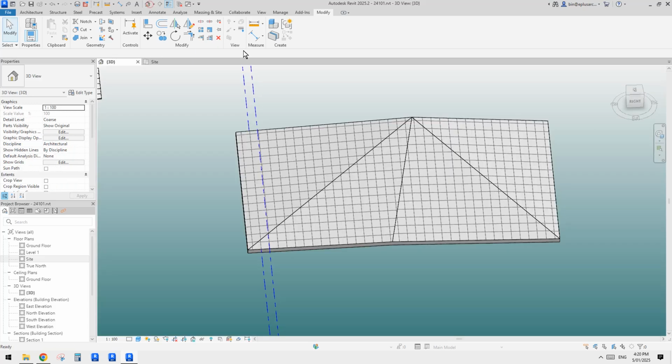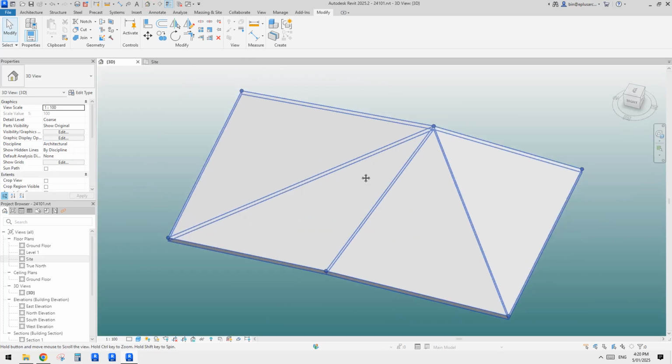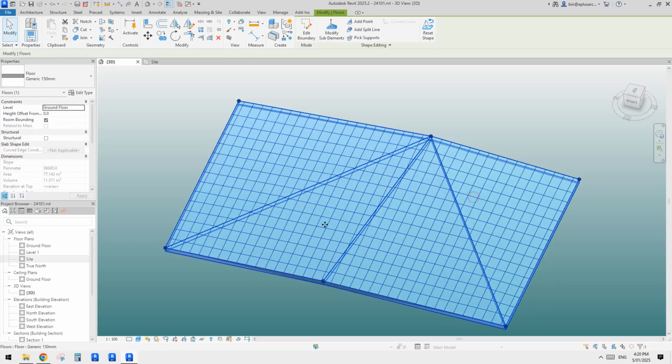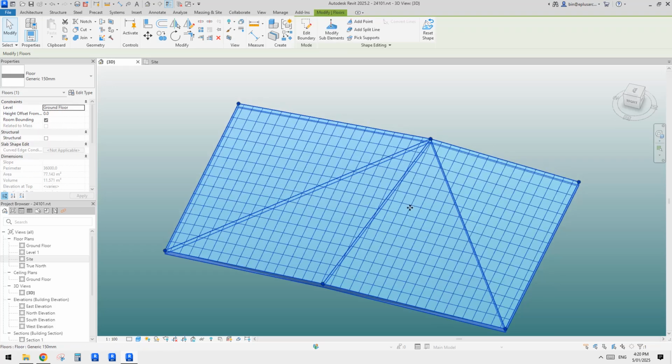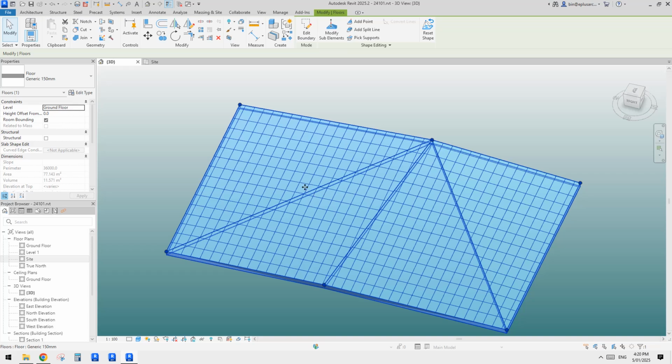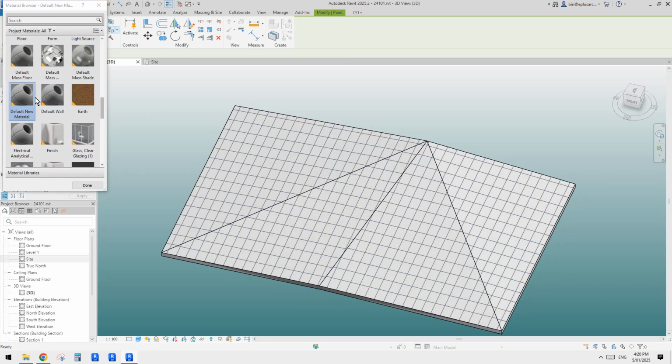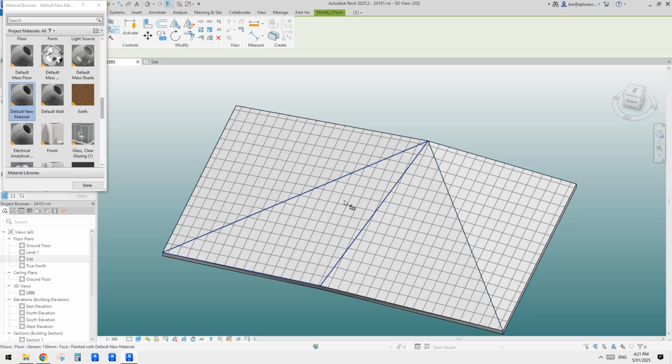I think what we can do is use the paint tool to override, because currently all the materials are the same and they are kind of linked. So this is why sometimes when we move a pattern, it will affect the pattern on the other surface. So what we can do is paint the same material here, same as this one, but paint it again. Which means it will overwrite the material on this surface, and they are all individual.